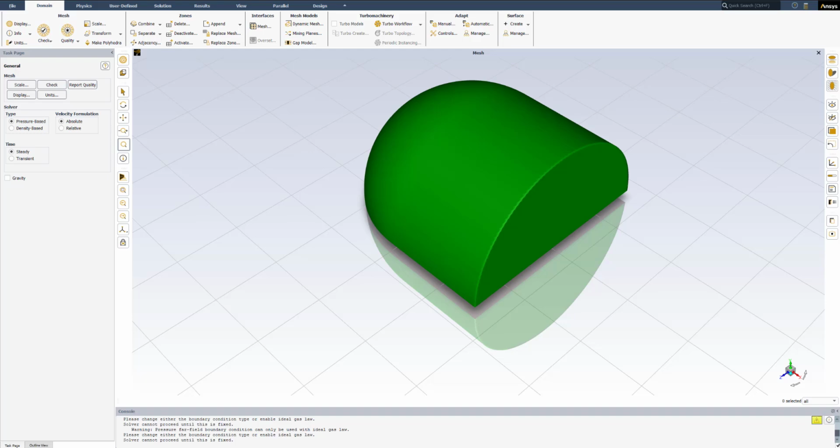This is part 2 of compressible flow simulation in Ansys Fluent. I'm going to set up and run this external compressible flow simulation here in Ansys Fluent. So in this tutorial, I'm going to set up and run a transonic turbulent flow simulation around the wing using this software, Ansys Fluent, and we will learn how to configure compressible flow, apply aerodynamic boundary conditions, and use the K omega SST turbulent model. So without further delay, let's get started.